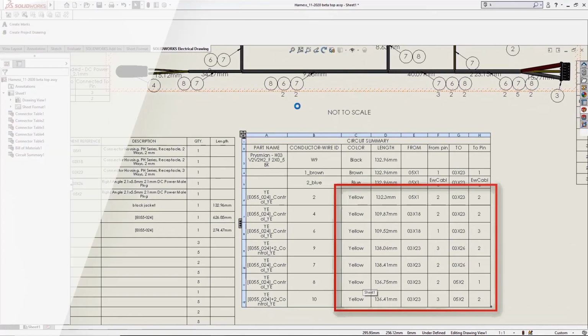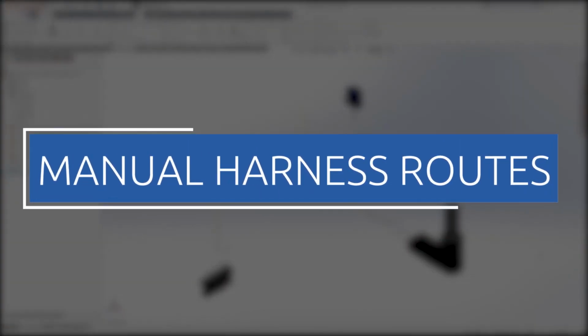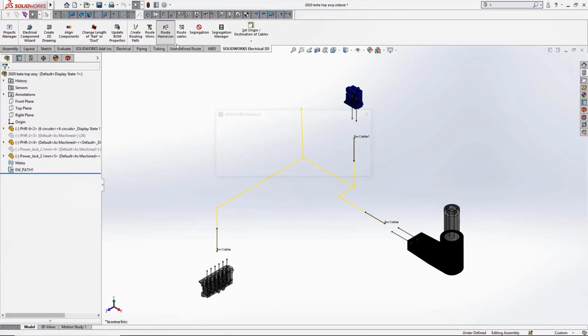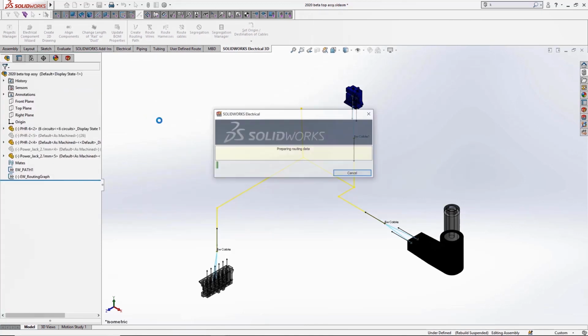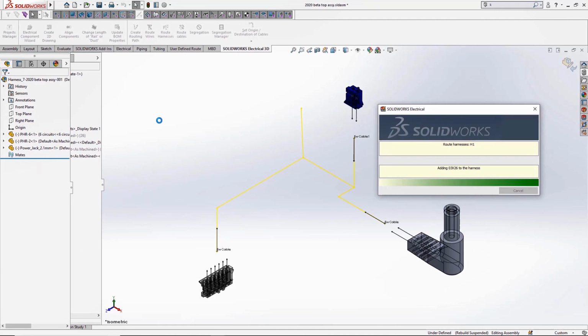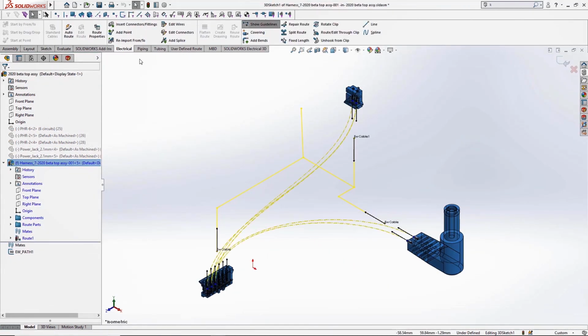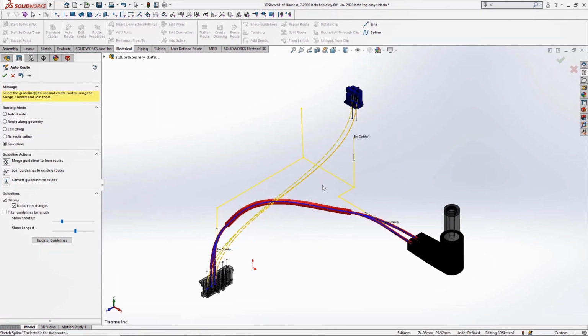products to market quicker. In SOLIDWORKS Electrical 2020, you now have a new routing tool at your disposal. Opt to finish harness routes manually by adding only the components to the harness, creating guidelines for connections. This is particularly useful for disjointed routes, as well as more complex looms, giving you more control on the routed harness connections. Fanouts for multi-pin connectors are also included to make the workflow even more efficient.